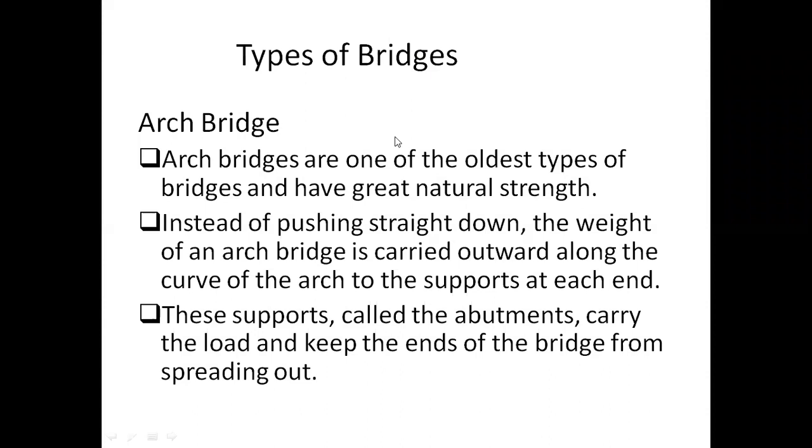Types of bridges. You will have an arch bridge. Arch bridges are one of the oldest types of bridge. I think many of you know about the arch action. What is the major advantage of an arch action? Arch action has more advantage than the normal beam, because arch will have very little deflection.